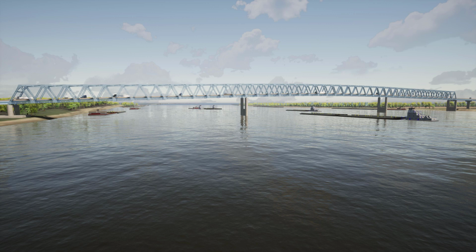So obviously, again, in preliminary engineering, we want to sort through alternatives, looking at things like quantities for cost estimates, preliminary analysis, sizing members, and looking specifically, again, with this type of structure, major river crossing, a lot of public involvement, environmental concerns, and in this particular situation, barge traffic. So being able to have these images to work with our public and other stakeholders within the project.